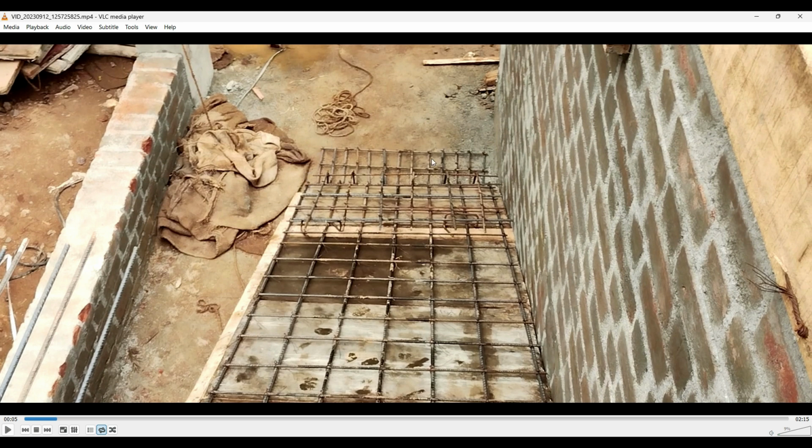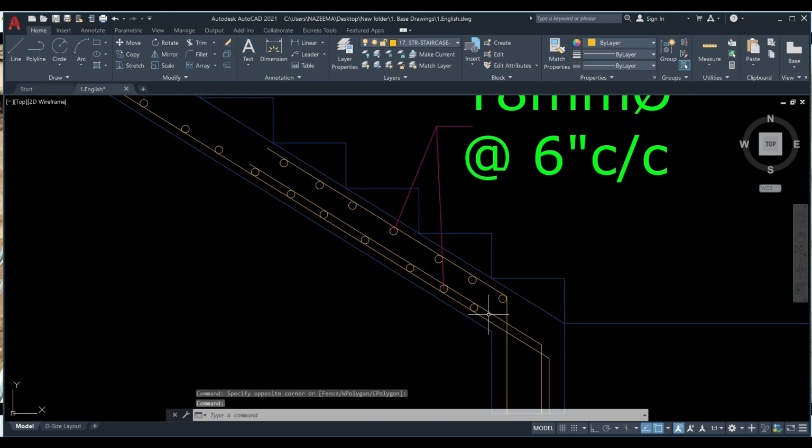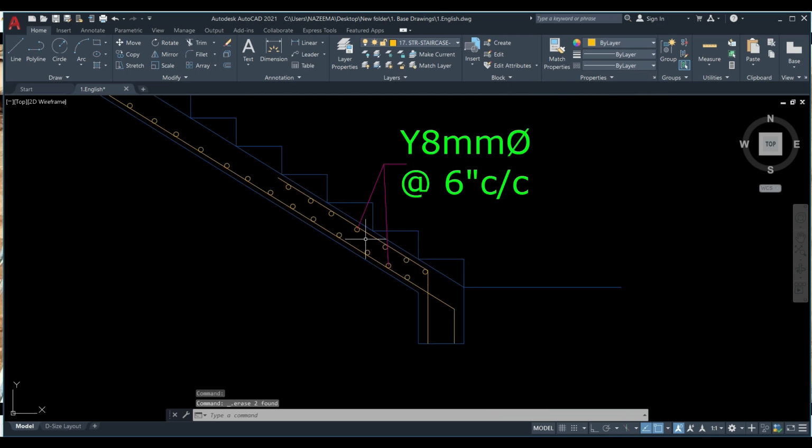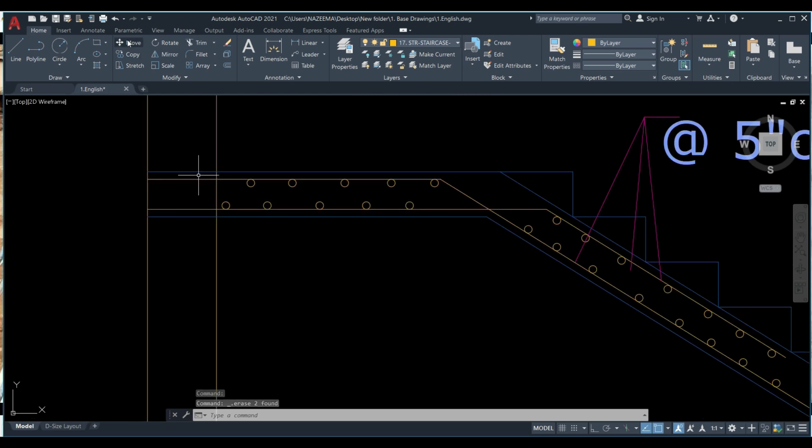Okay, to fill up all that space which is there in the bottom, and there you can see a top mesh is there, and we have a staircase. So in this particular staircase, you're seeing this top mesh, you're seeing the bottom mesh. What you are not seeing is this additional rebar, which is not required from our end. Okay, so this mesh is there at the top, this mesh is there, and that same thing is happening here. It is going and ending in a support part. Okay, a hidden beam part, it is going to go and end there.